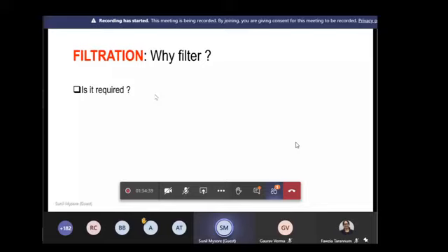You also have these days something called a centrifugal filter, which eliminates this entire requirement of opening and closing. But the problem is there's nothing in the filter. It's just a mesh. Essentially, you use the centrifugal force of the water to push the water, and the heavy material is going to fall down. But with any kind of clogging, the entire water will go down. I'll come to that later.